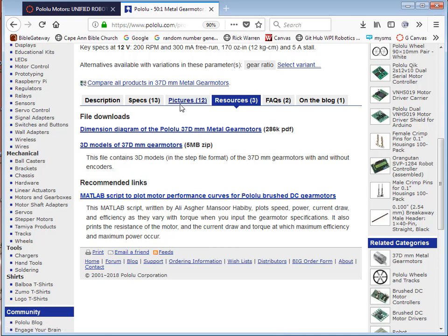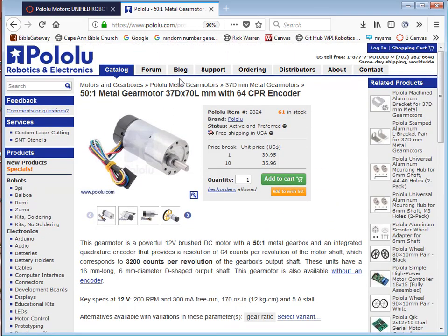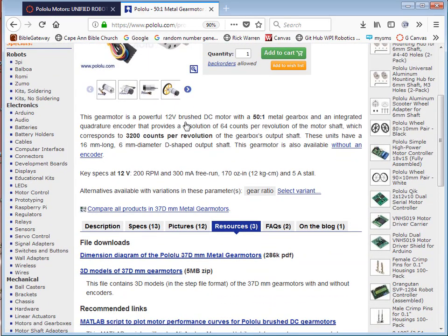But again, because the relationships between the speed and the torque, and the current drawn and the torque, are both linear, if you have these points, then you can easily write the equations. And if you want to plot, you can just create an Excel file to do that.